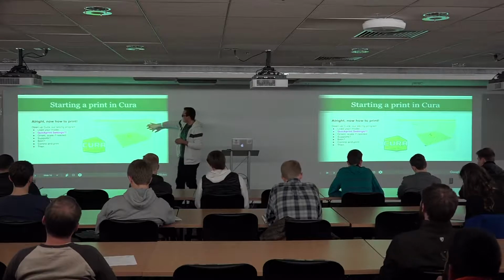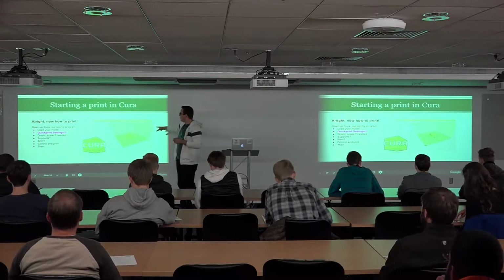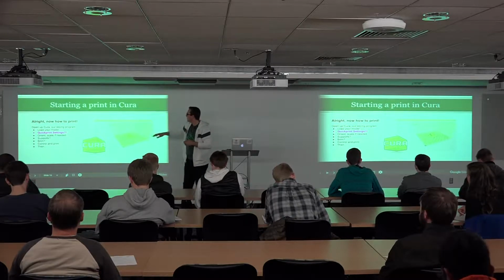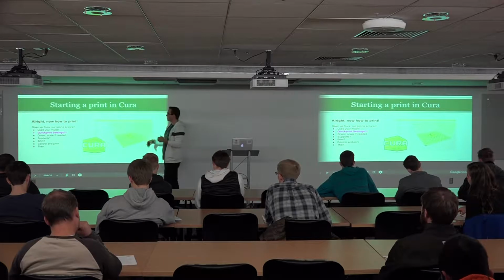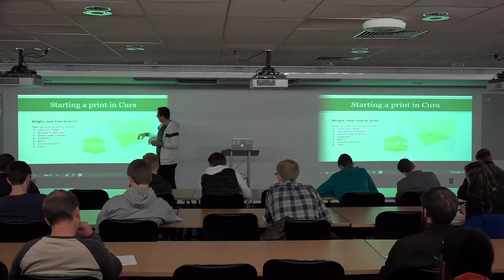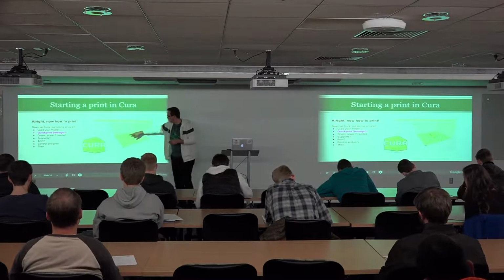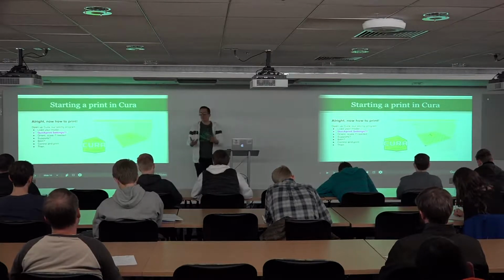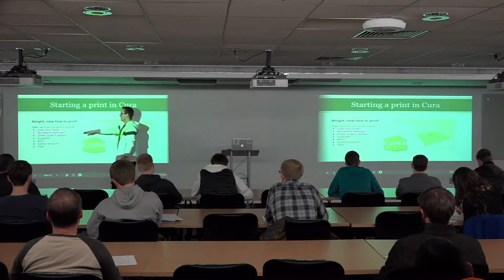And then I think you've got another obvious answer on your quiz here. Printing in Cura. There's a couple things you want to do. The first one is very obvious. Load your model. So get your STL file, make sure it's all good to go. Throw it in here. It'll show up on the build plate, which is the same size as the printer that you're going to use. And then you want to go to quick print settings.